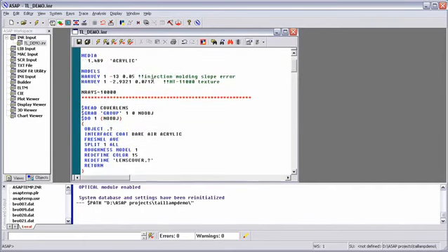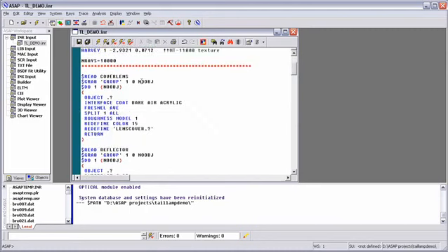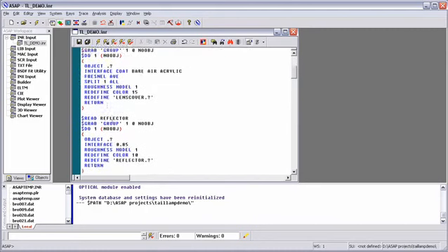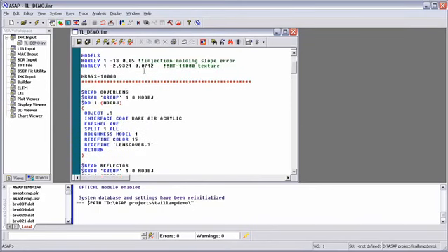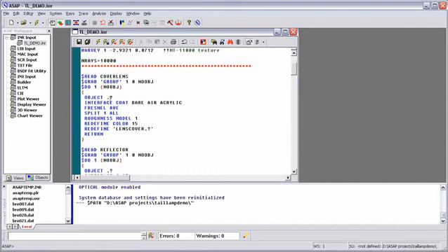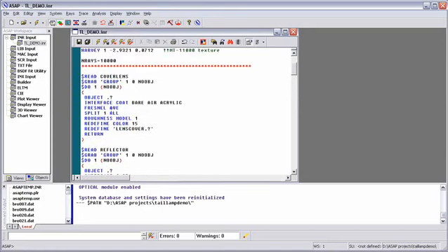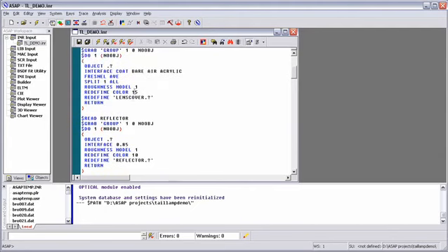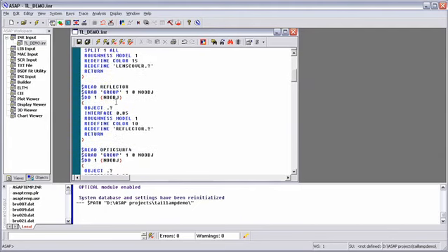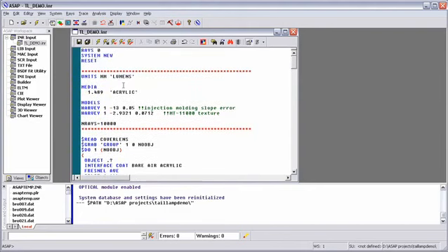I've set up my script file ahead of time to simulate the part, and we're going to simulate the cover lens, the reflector, and the optical surface that we just created. One of the things I mentioned before is that we skipped the material assignment in the IGES translator, because inside my script in ASAP I can use this do-lib construct that allows me to set my material properties for each one of those components. This allows us to change material properties quickly on each component, and we'll look at that a little bit later.